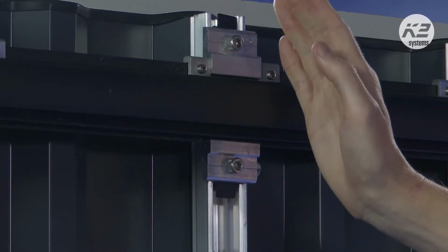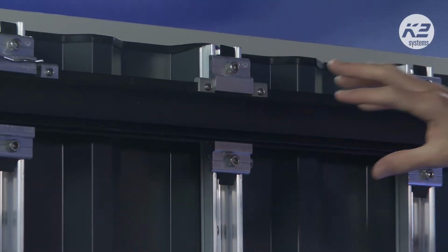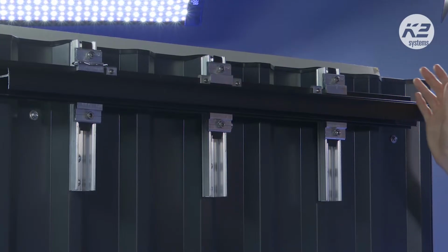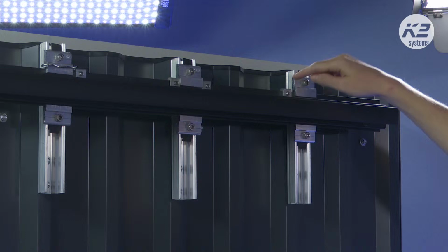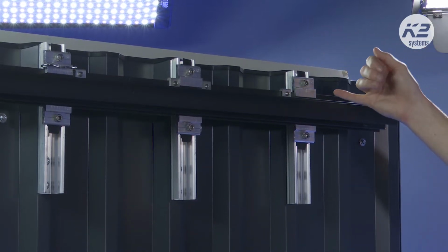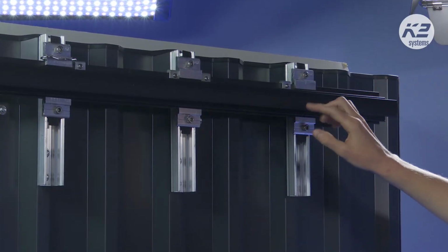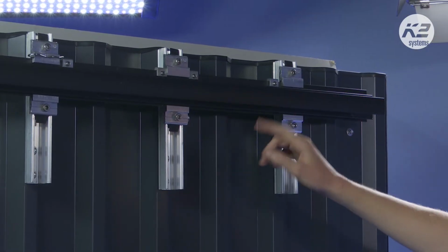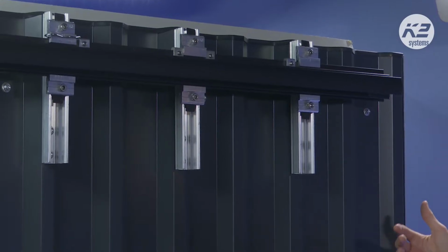This will ensure that if the rail expands in any direction, it is held here, and the expansion will only be seen on the other ends. We do also have a little stopper sometimes on the end, which you'll see occasionally in the software. The idea is we want to limit the amount of force that the expansion of this rail has onto the underlying roof, or in this case, the underlying facade structure.